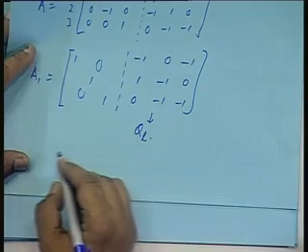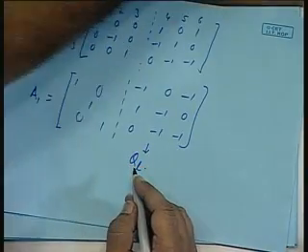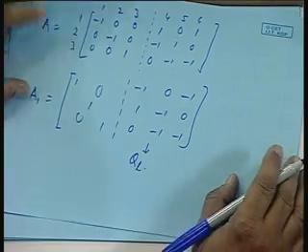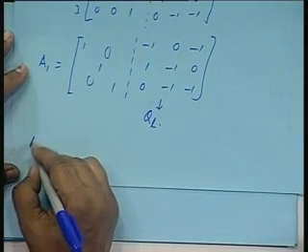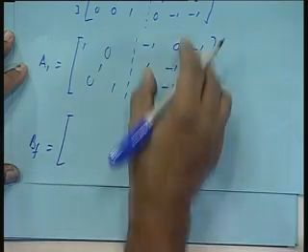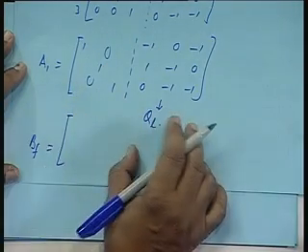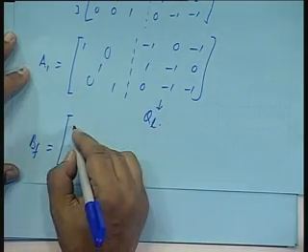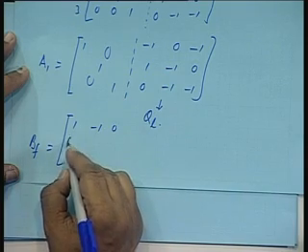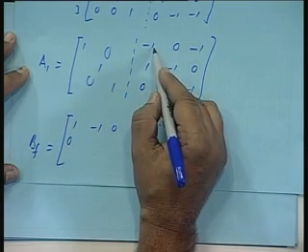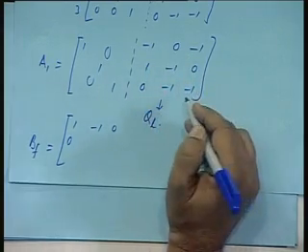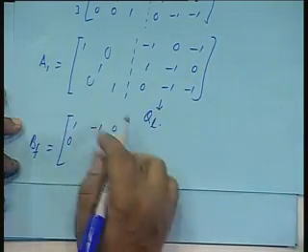So, this is QL. If you know QL, you know BT and hence BF. BF, if you remember, will have the transpose of this coming first, followed by a unity matrix. So, it will be 1 minus 1 0, then 0 1 minus 1 0. Just put opposite signs and then transpose, you will get this matrix.